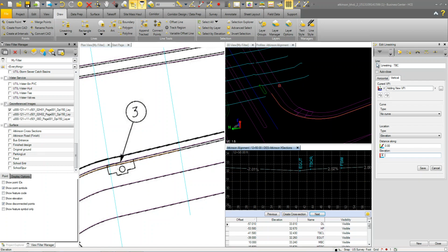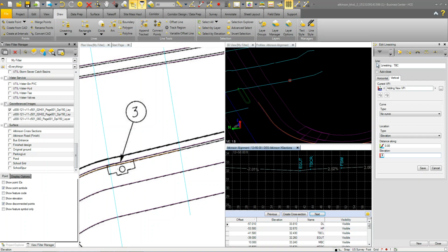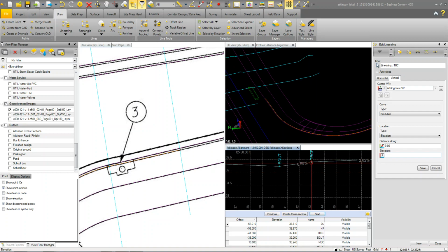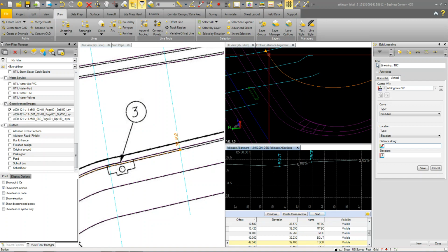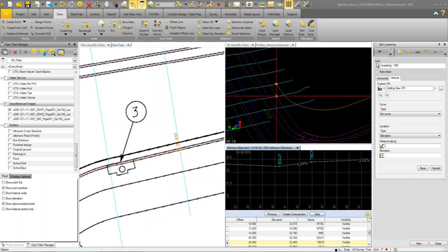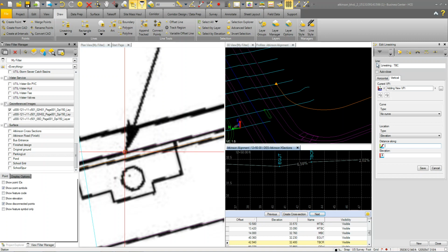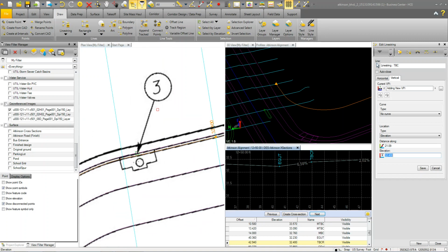because it's kind of hard to see where that top back of curb is because it's pretty shallow of a break, I'm just going to grab it from the typical cross section. So when I click on here, it actually defines that alignment, and it picks up that elevation point and picks up that elevation for me there. Now I need to come down here and put in a point, and it's actually on the PC of the curb, so that's number 3. So I'm just picking that point.